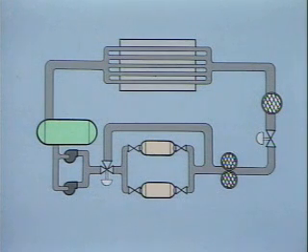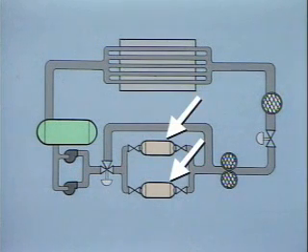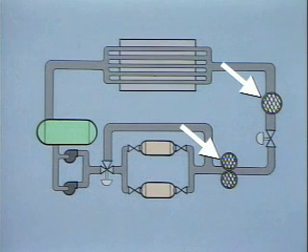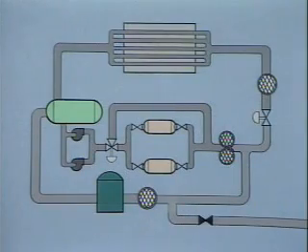A sensor at the generator outlet detects the temperature of the cooling water. If additional cooling is required, the sensor adjusts a temperature control valve that redirects the water flow through heat exchangers. A pressure control valve maintains the proper pressure in the system as the water is recirculated to the stator. This system also includes filters to remove magnetic particles and other contaminants. Another component in the cooling water supply system is a demineralizer.